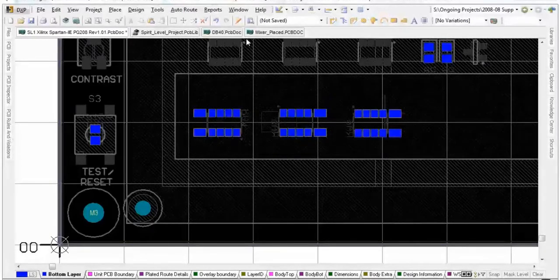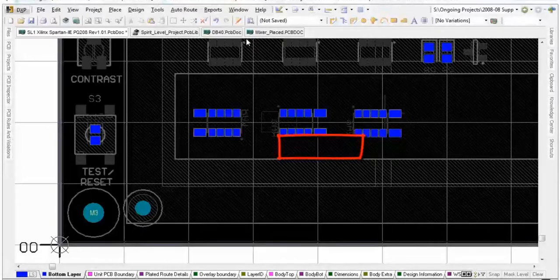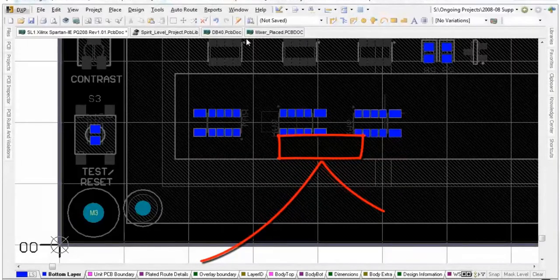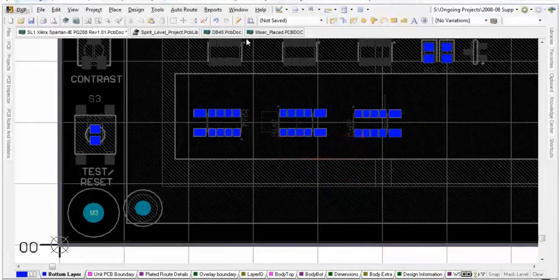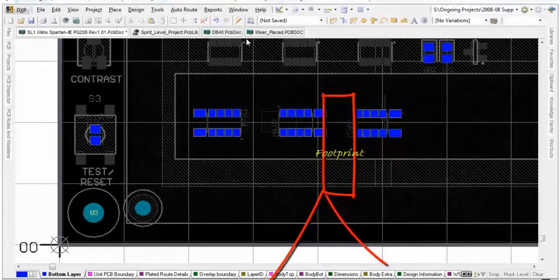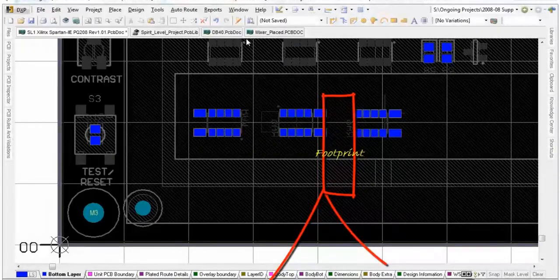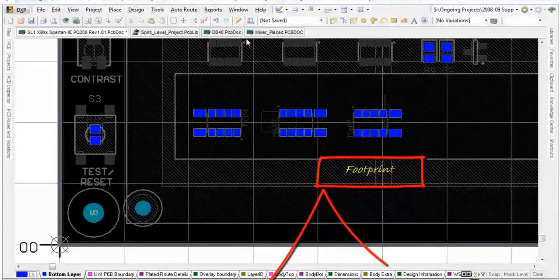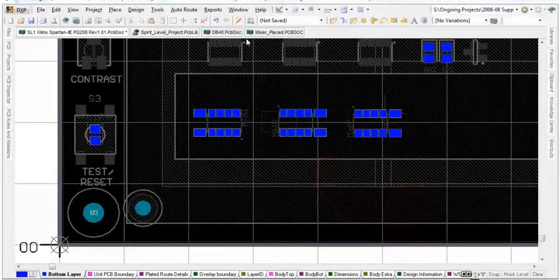But before we start asking ourselves how, we should first deal with the question of why the alignment should be checked. There are various different soldering techniques used in the manufacturing process, one of which is wave soldering. If a PCB is to be successfully passed across a wave, there are always a number of conditions that must be respected. And one of these is the position of the components. When components are laid directly across the waves, shadowing can occur, whereas laying them lengthwise along the waves can lead to a short circuit at the end pads, against which a solder thief should be inserted.